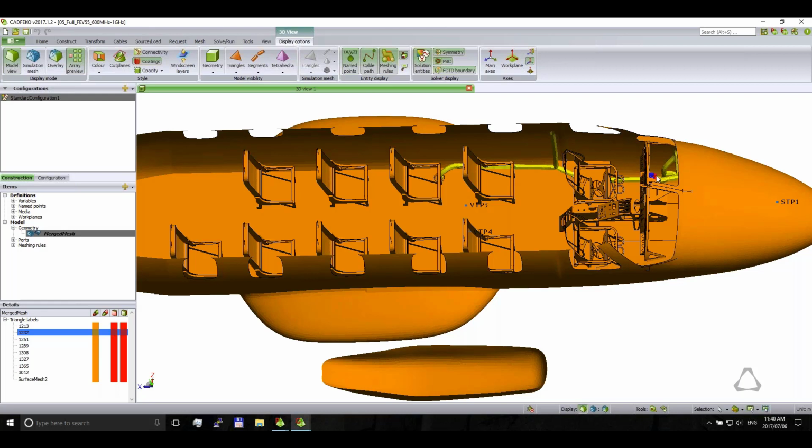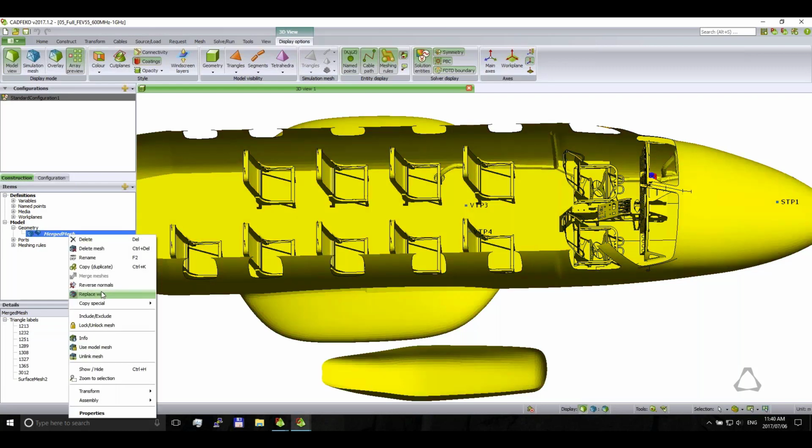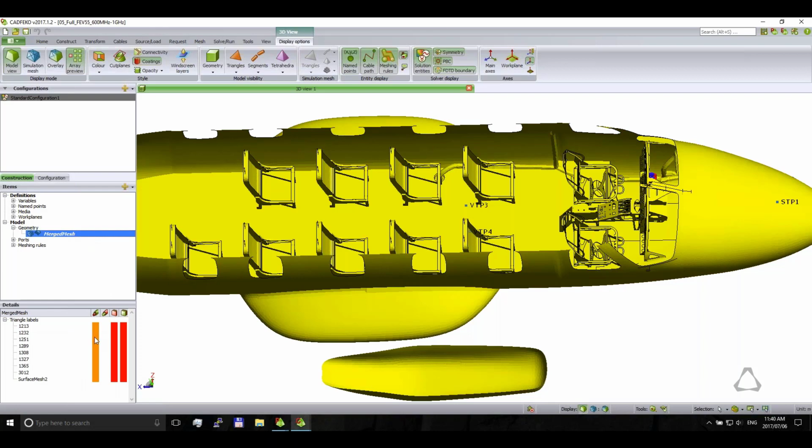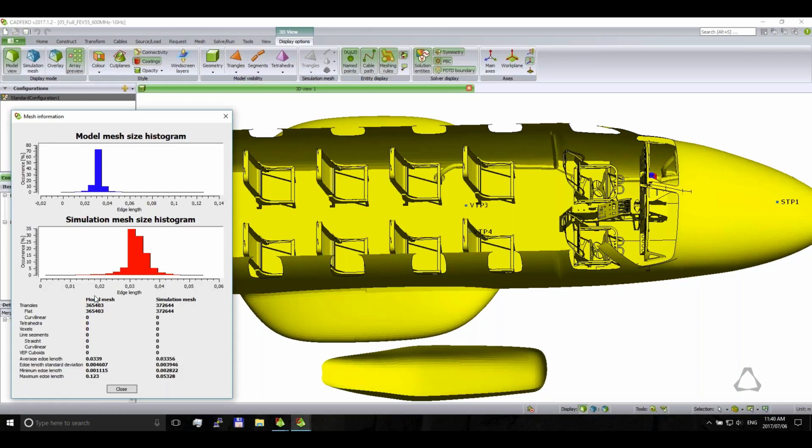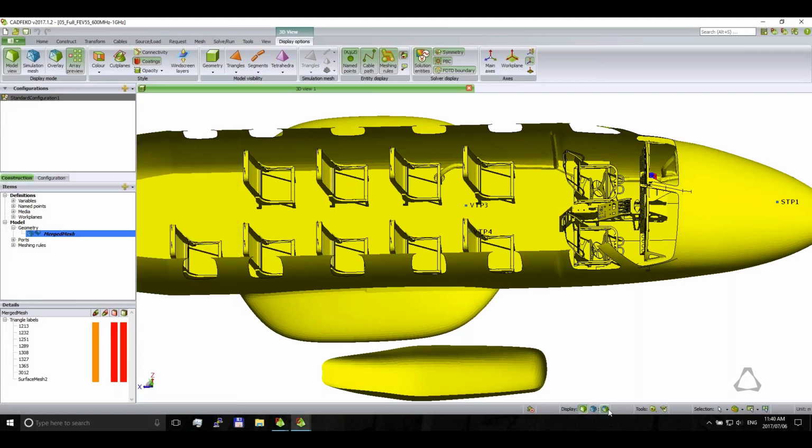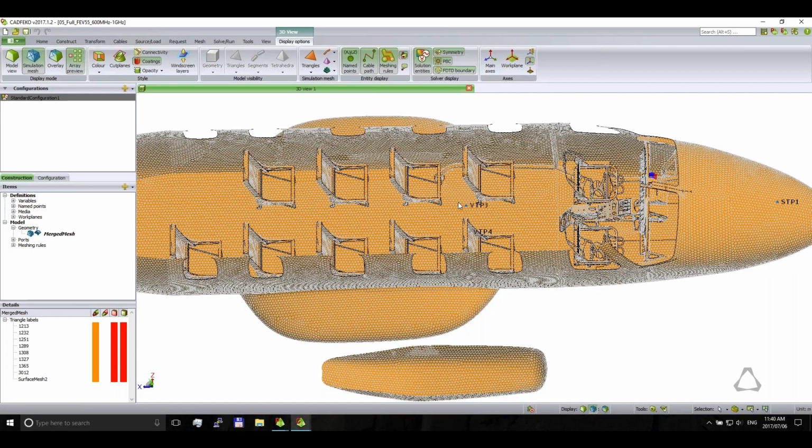And here you can see the port where we calculate the induced current. This model is from the highest frequency band. If we look at the meshing info, we'll see that the average triangle size is around about 3 centimeters, and that we have about 370,000 triangles in the mesh. Let me also view that here quickly. You can see the mesh that we use for the simulation.